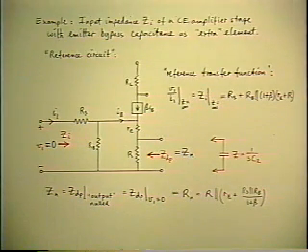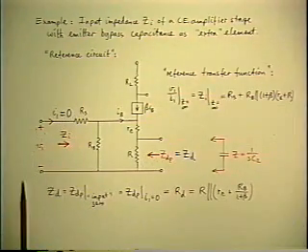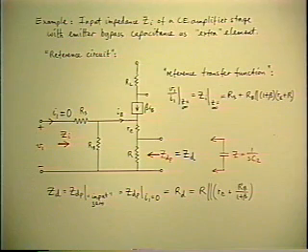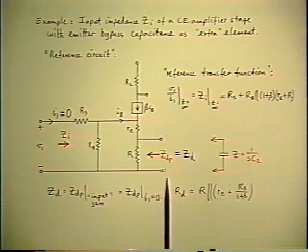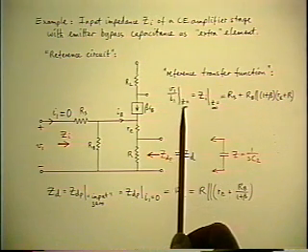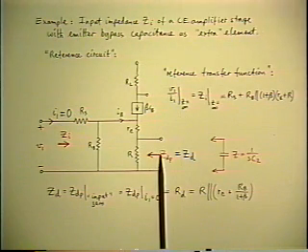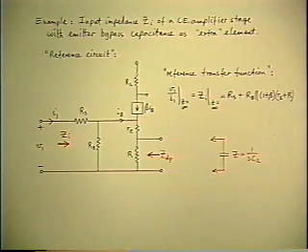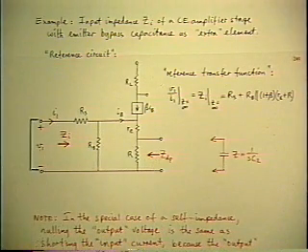And we've already seen in the previous picture that you get the answer for ZD if you open the input. So that's a shortcut. When you're calculating the correction factor and the two driving point impedances for a self-impedance, you calculate the ZD, single injection, and you open the input, and you calculate Zn, also single injection, by shorting the input.